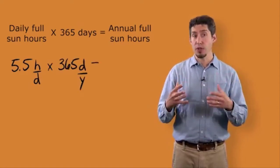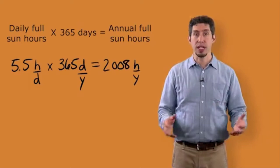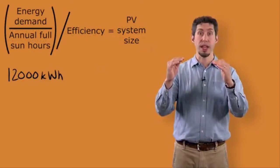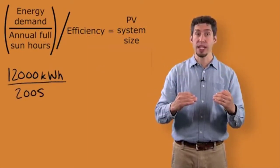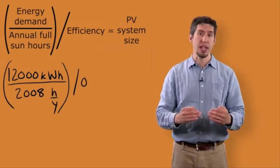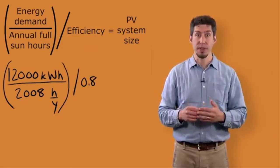So if we do that and multiply 5.5 by 365, we get 2008 full sun hours, the annual sunlight energy that's available. We then divide the 12,000 kilowatt hours of electricity demand of our energy by those full sun hours of 2008, and then divide again by the external efficiency loss, where we get 80%. So we divide by 0.8. So that's the efficiency of the system after we take into account those losses we discussed previously.